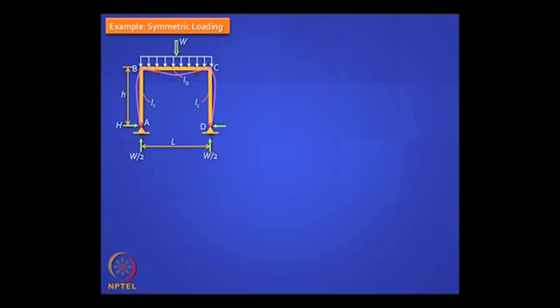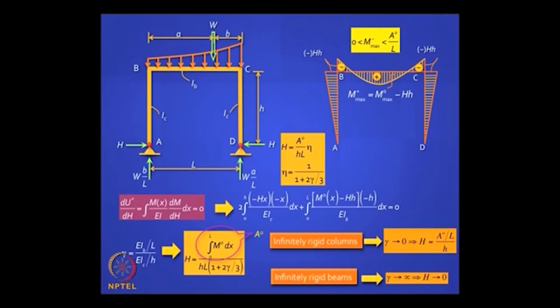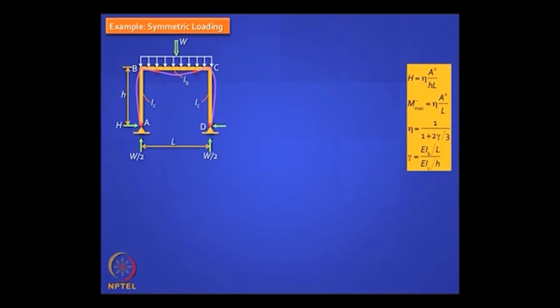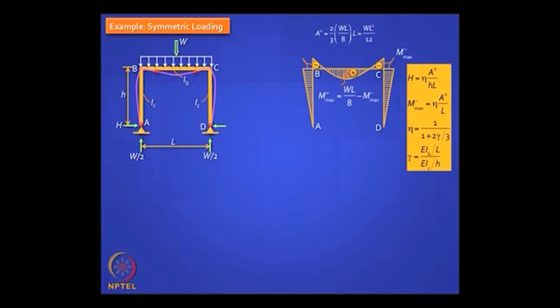If you recall, this is the general bending moment diagram. So here you have a parabola due to a UDL. So what will it look like? These are your general expressions for any symmetric loading, right? So do you agree this is the bending moment diagram you get?